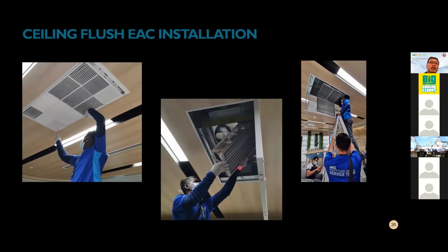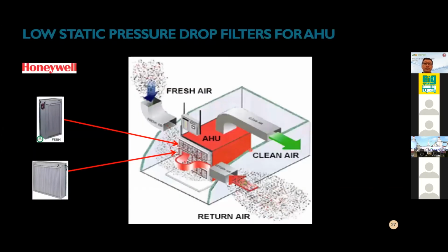That is a corona charging wire, high voltage. There's a fan here. The air will be drawn in and filtered, then goes through a sterilizer for decontamination, then recirculated back into your office area. Then you get a very high air change.